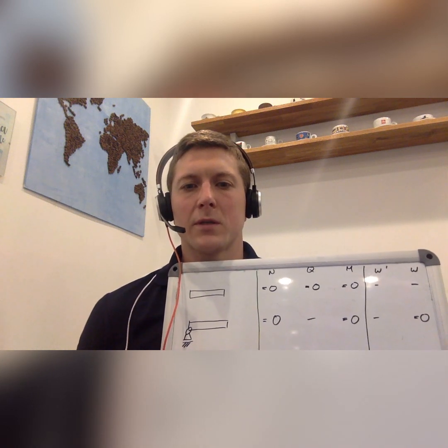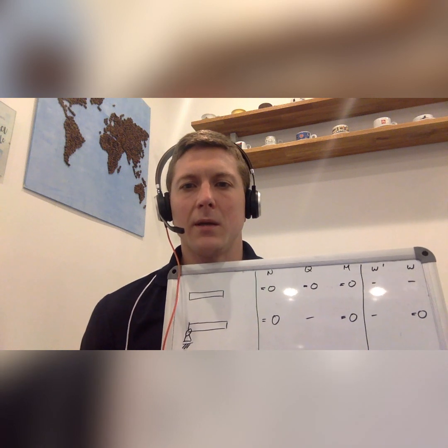Because of this discrete force, this bearing force in z direction, we cannot state in advance that Q, the shear force at this position, in this case x equals 0, would be 0. That is not possible, because the shear force at that position is identical to the negative bearing force. That is what we can state. But we cannot say Q equals 0.